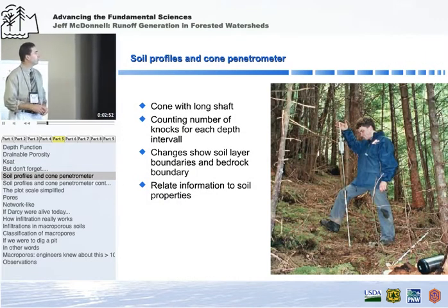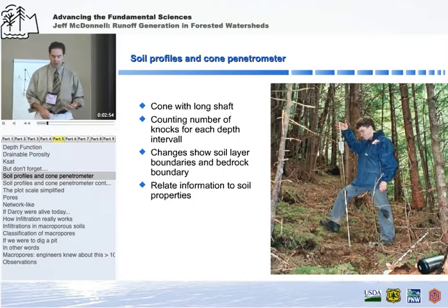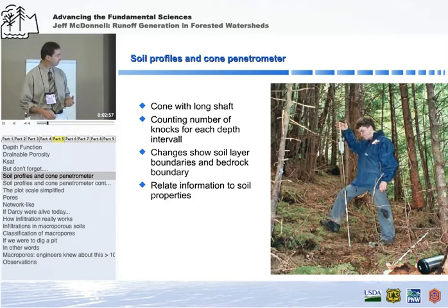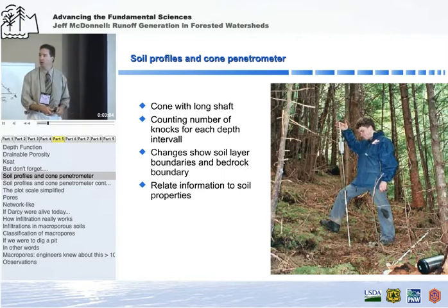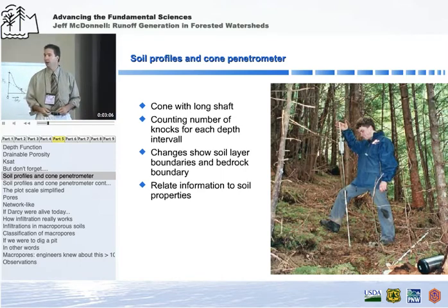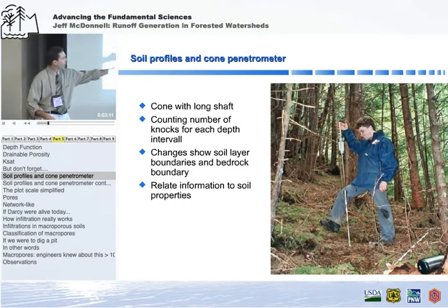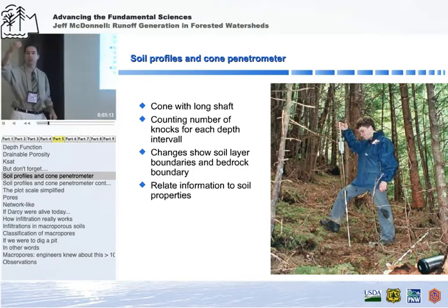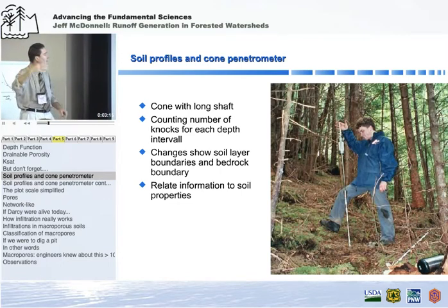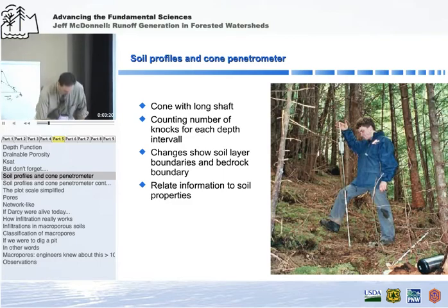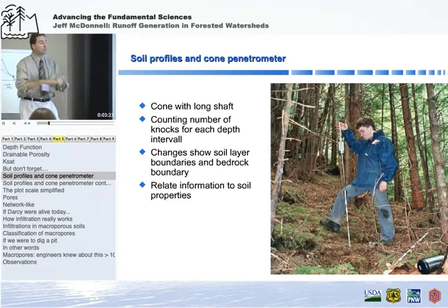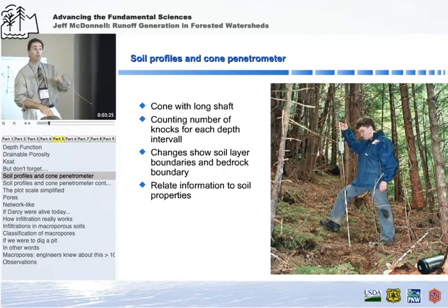Now, in terms of bulk density, one of the better instruments I think that one can use is what's used a lot in Japan. It's a comb penetrometer. They call it a knocking pole penetrometer. This is a device you might have used in your studies, particularly if you're coming from a soil mechanics or civil engineering background. But essentially it's a 5 kilogram weight that is dropped from a known height onto a disc, and you count the number of knocks it takes to plunge the rod vertically through the soil profile.